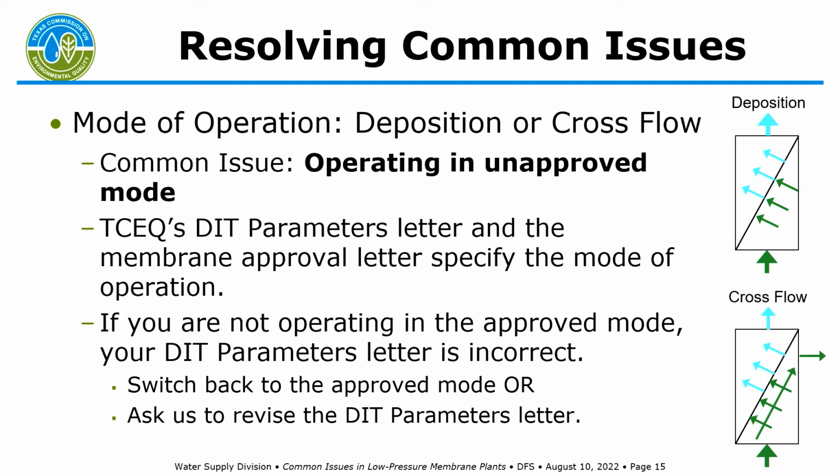The real issue here is if you're in crossflow mode, which is also sometimes called recycle mode or suspension mode, because of the way it works, it actually concentrates pathogens on the upstream side of the membranes.